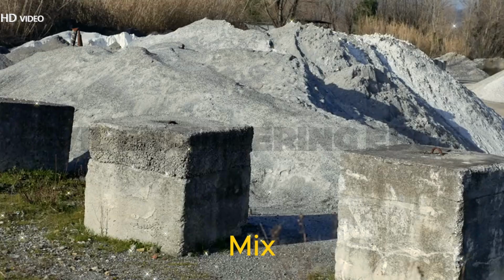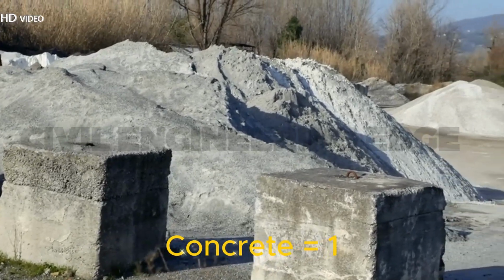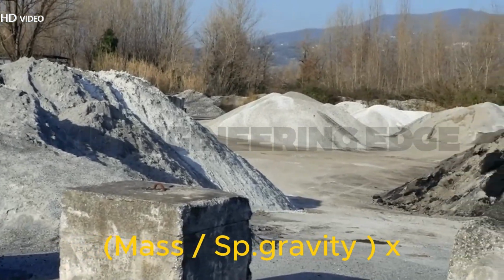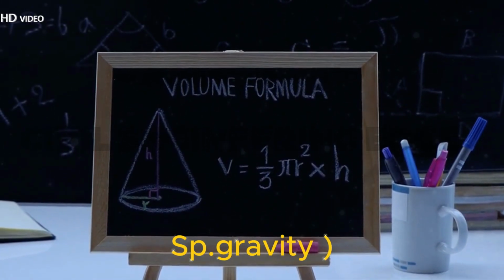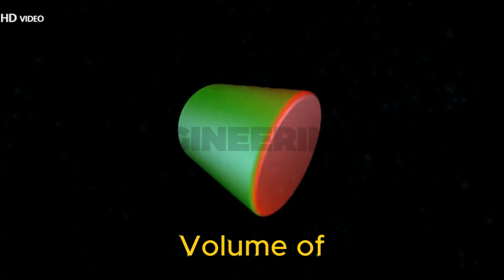6. Final mix proportions. Volume of concrete equals 1 m³. B. Volume of cement equals mass over specific gravity times 1/1000, equals 315 over 3.16 times 1/1000, equals 0.099 m³. C. Volume of water equals mass over specific gravity times 1/1000, equals 157.6 over 1 times 1/1000, equals 0.158 m³.